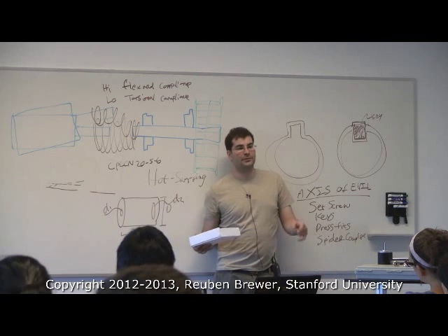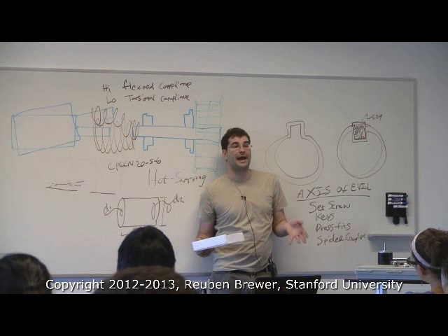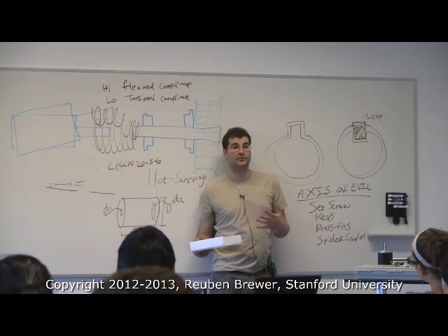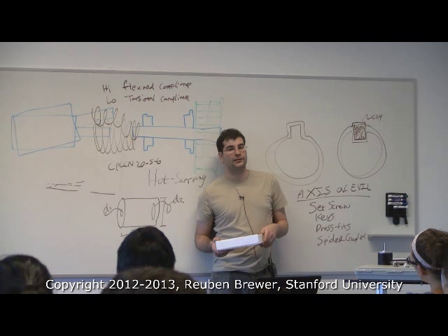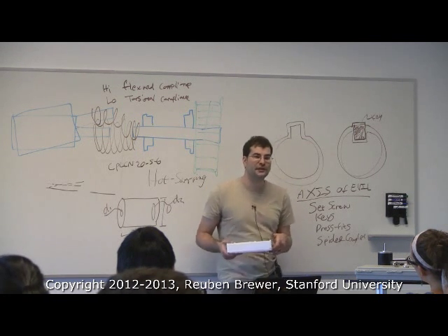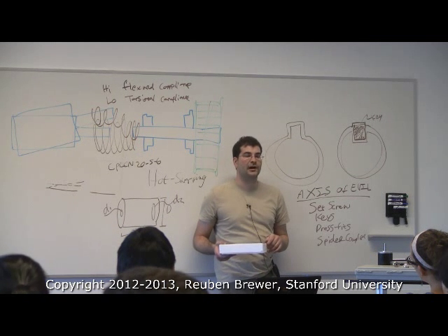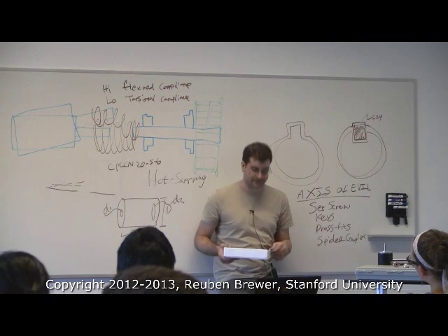Then you look up the coupler, and the coupler guy is going to say 2 Newton meters max. And if you have 3 Newton meters required, then you can't use it. Oh, so you do it the other way around. You don't go from the motor, you over-dimension the motor and set your thing based on that. Yeah, you always over-dimension everything. It's called factor of safety. If you need X and you give X, your robot will fail half the time. You need like 2X or 3X or 4X.